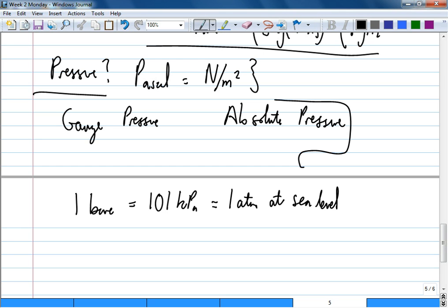There's a coiled piece of spring in here, with a channel opening inside. As the pressure builds up inside, that piece of spring wants to straighten out, just like when you blow the party whistle. And when that wants to straighten out, it will move this down. That's how it works. So it relies on the pressure difference between inside here and the atmospheric pressure. Right now, inside here and the atmospheric pressure is the same. That's why it's reading 0.